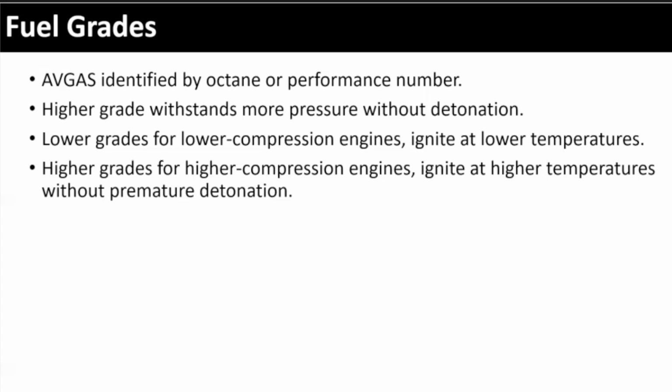Okay. Higher grades withstand more pressure without detonation. We'll talk a little bit about detonation in a couple of slides, a little bit further down. And lower grades are for lower compression engines, they ignite at lower temperatures, right? Some planes are going to burn hotter, some are going to burn cooler. You want to make sure you have the right grade of fuel for the engine type for your aircraft, right? So your manufacturer documentation is going to tell you what to use. Use it. Don't try to save money by going to a lower octane fuel or a lower level fuel. It's not going to pay off in the end.